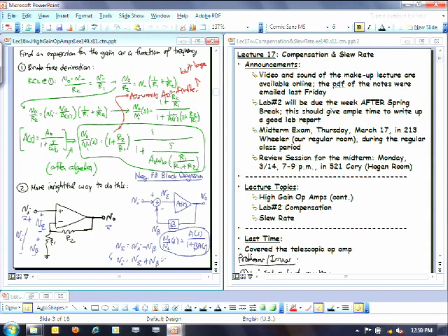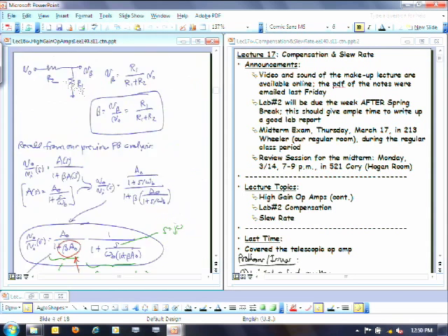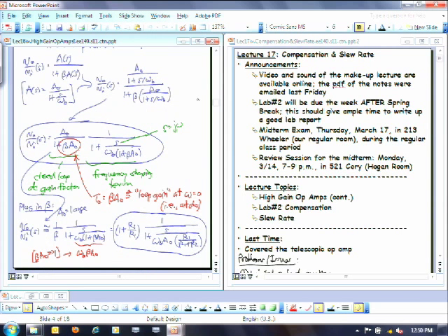And so using that, we can get the transfer function for this R1, R2 branch. That becomes beta. So beta equals V beta divided by V naught, which is just the voltage divider between those two resistors. Then we apply that standard feedback system block diagram equation and plug in all the values that correspond to A of S and beta. When we did that last time, we ended up with exactly the same expression that you get using the brute force nodal analysis technique, but perhaps we did this a little bit faster by inspection.